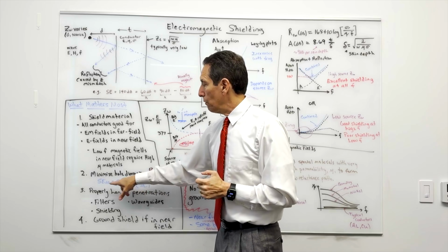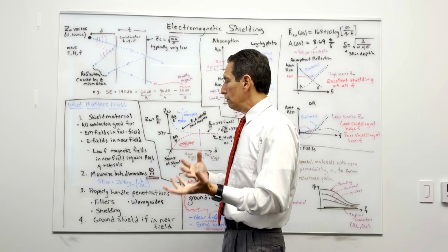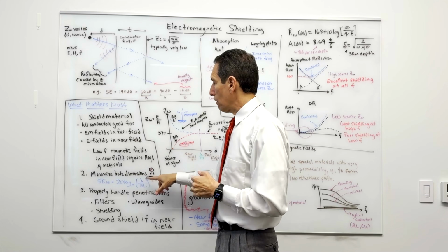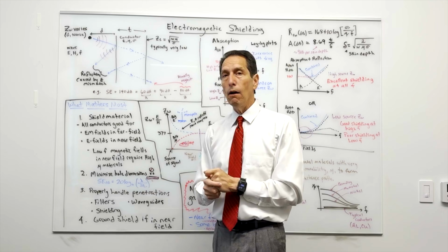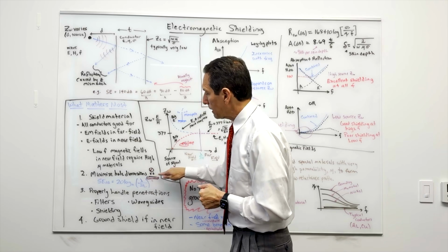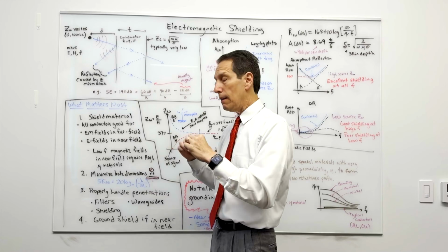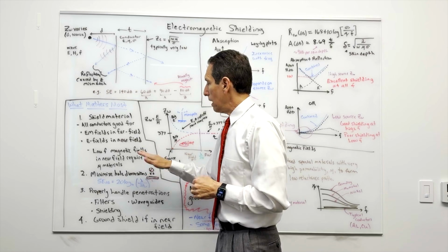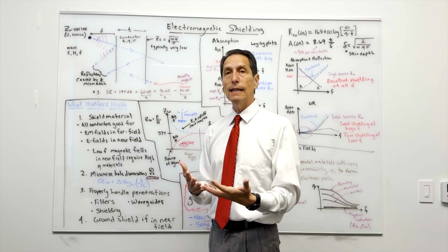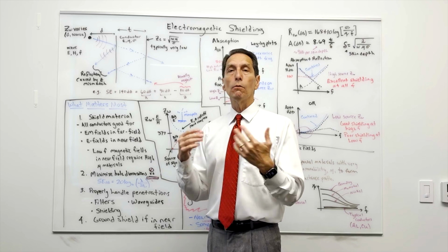And so you can calculate the shielding effectiveness as simply 20 log of the wavelength over 2L, where L is the maximum distance across the hole. All right, so maybe corner to corner if you had a slot like this. And you can see what kind of shielding effectiveness you can get with these type of slots or imperfections.